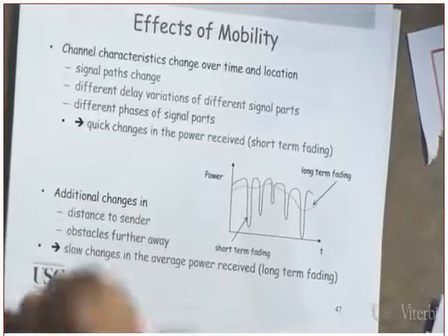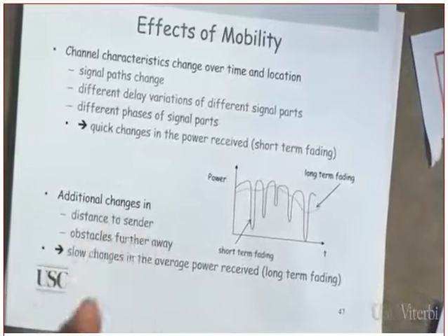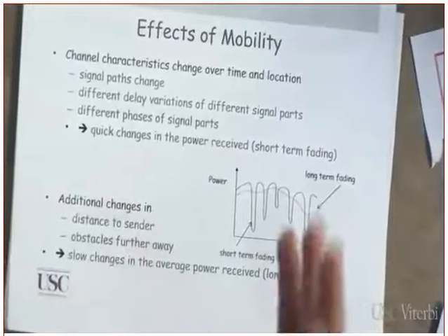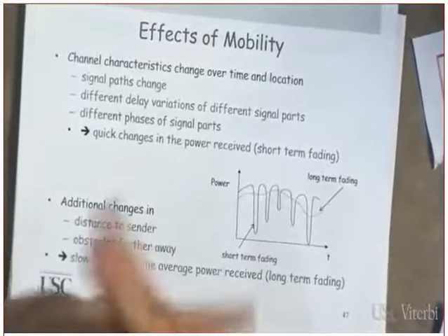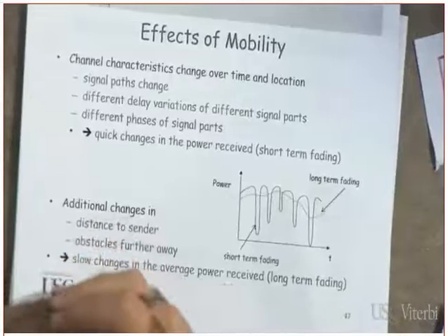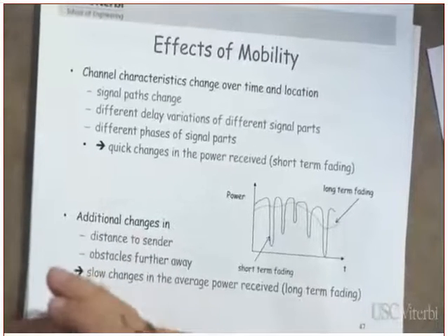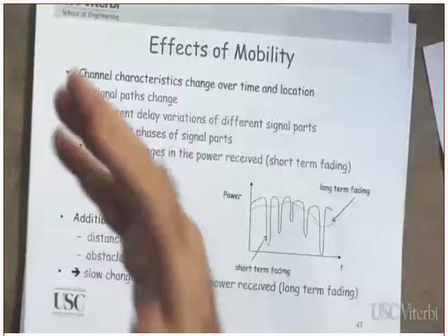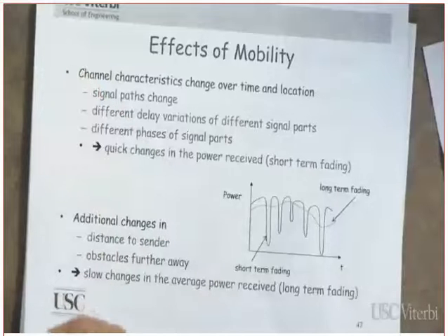What is the dynamic range of a receiver? We are going to designate it later on. Don't worry about it. Right now, just listen to me. The dynamic range of the receiver will be designated by DR, and it is measured in dB, which means what? It's not a power. It's a ratio. Did you understand that or not? dB stands for decibels.